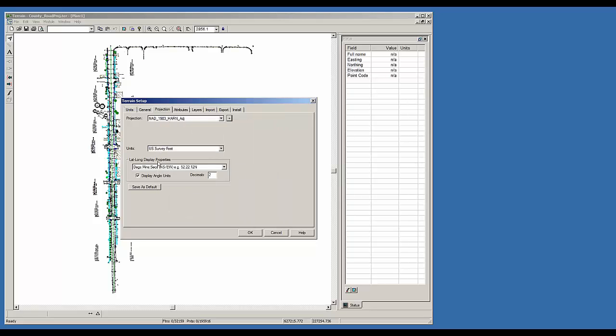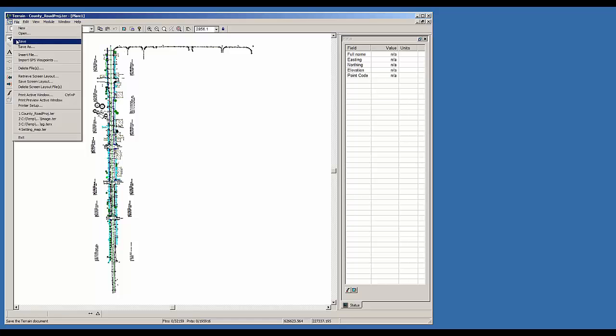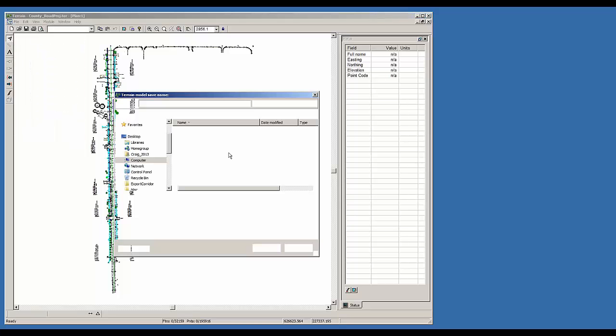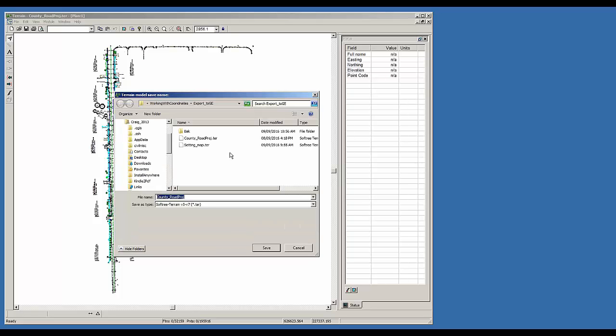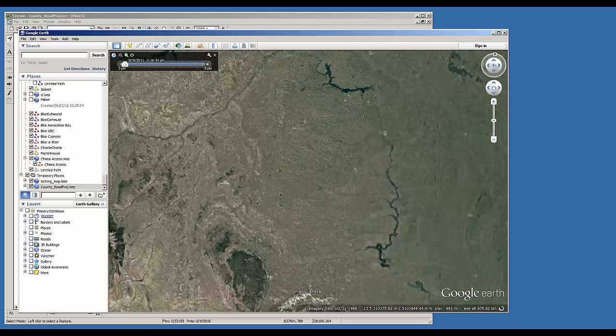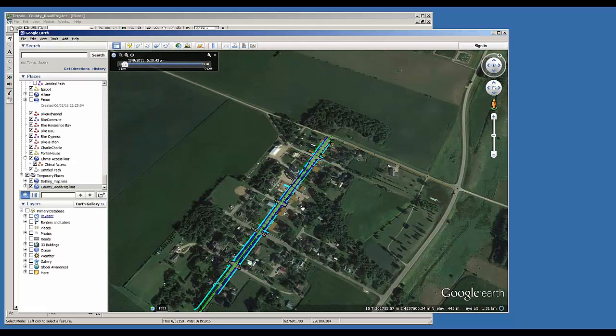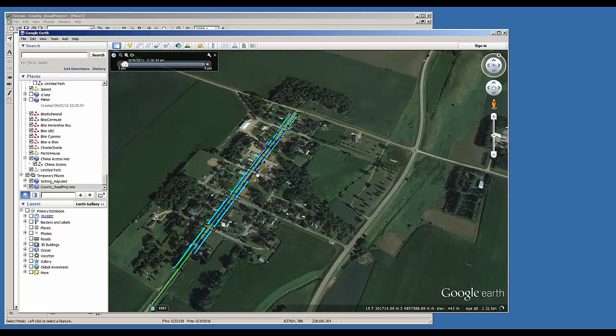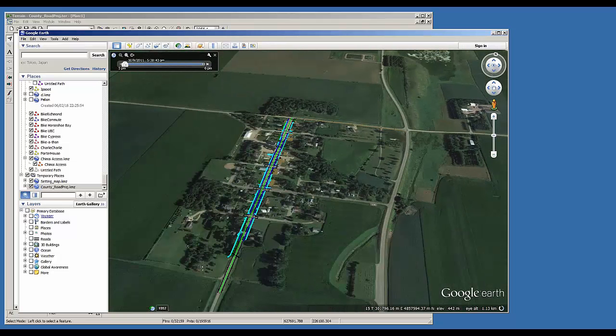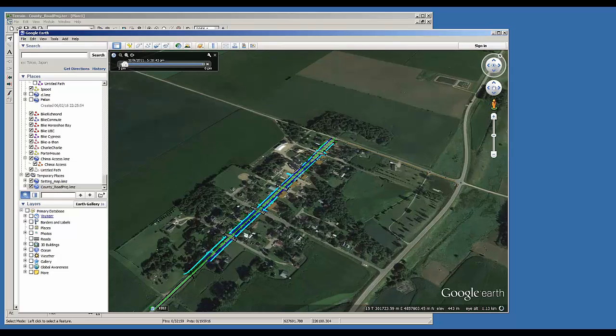So we've got a custom coordinate system. In this case, it's in U.S. survey feet. And just as I did with the block survey, I can just save this one out to Google Earth and make sure that it lands in the right place. Just as a check, KMZ, again, Google Earth. Saves everything out. There's more information this time, and it's going to take us somewhere else in North America and plop us down to a county road project in Minnesota, but we know we've got the right coordinate system by simply doing this. For some reason my Google Earth is not letting me zoom in here. Anyway, you get the idea.